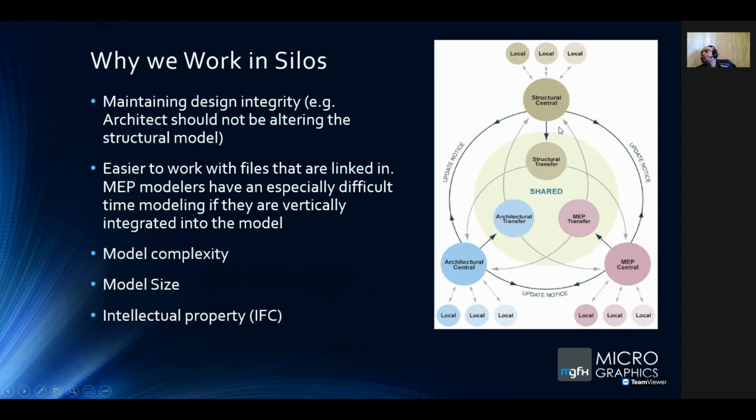So what's great about BIM 360 is that there is even an automated clash detection that can be set up. That's what we call BIM 360 Coordinate. And as the models are shared with the other teams, clash detection is automatically updated. So the BIM managers from each silo can immediately see what impact the other disciplines' models will have on theirs.